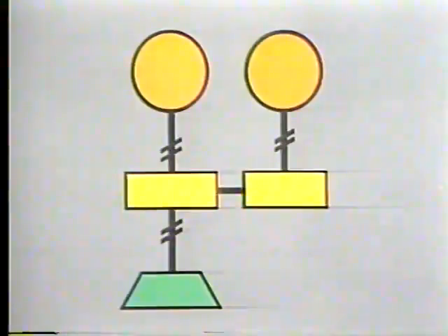In simple terms, a cascade control system is a system in which the output signal of one controller establishes the set point in a second controller. The output signal from the second controller operates a final control element. To understand what we mean, let's look at a logic diagram that represents a simple cascade control system. This logic diagram is similar to the logic diagram for the ratio control system that we looked at earlier, but there is one important difference.